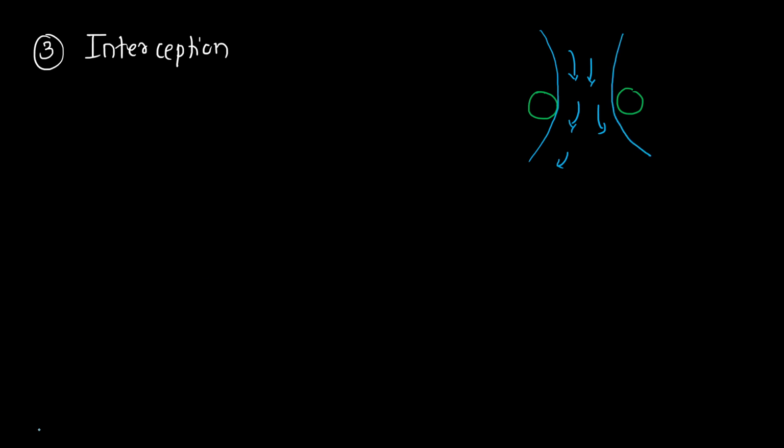Okay, so when the water will be flowing along with these particles, whatever small impurities are present, due to the force of attraction, these particles will stick to the bigger particles in the filter media. So this process which occurs due to force of attraction is called interception.